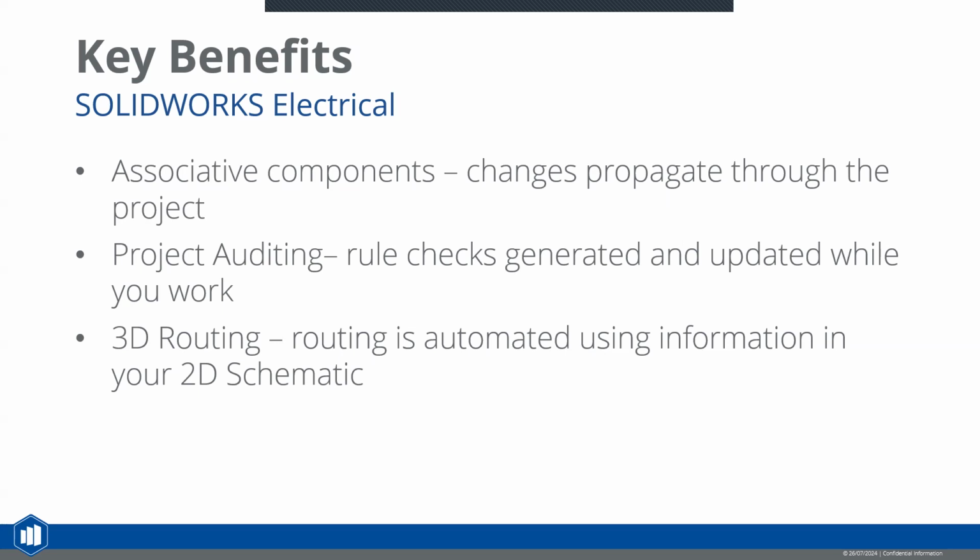Project auditing is another key capability here. So think of this almost like design rule check in SOLIDWORKS CAD. This is something that can basically view your projects, and if you've missed something, it will notify you in a report. So let's say I put down a wire and I did not give it a wire number. That would cause issues downstream in a manufacturing scenario, where I missed a wire because it wasn't in a report, right? This software is able to track that for you and let you know when that error has been made.